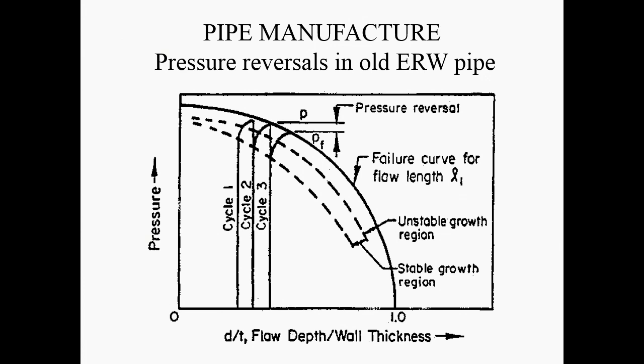So when we get to 1, the pipe is going to fail because the defect's all the way through the thickness. If you've got a defect in the system that reduces the wall thickness by a certain amount, then it's going to reduce the maximum pressure that you can put on the material before failure occurs. And we have a curve that goes like this, and you can prove that by simply applying Barlow's formula in most cases, reducing the pipe wall thickness by the size of the defect.